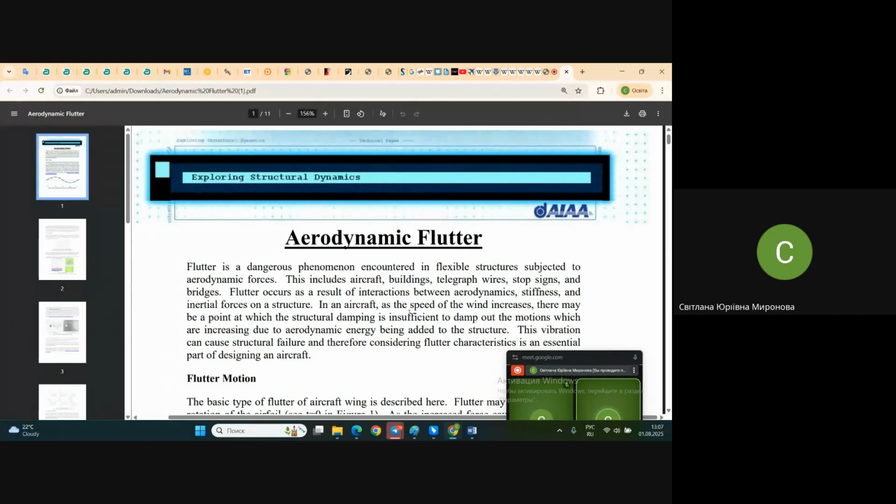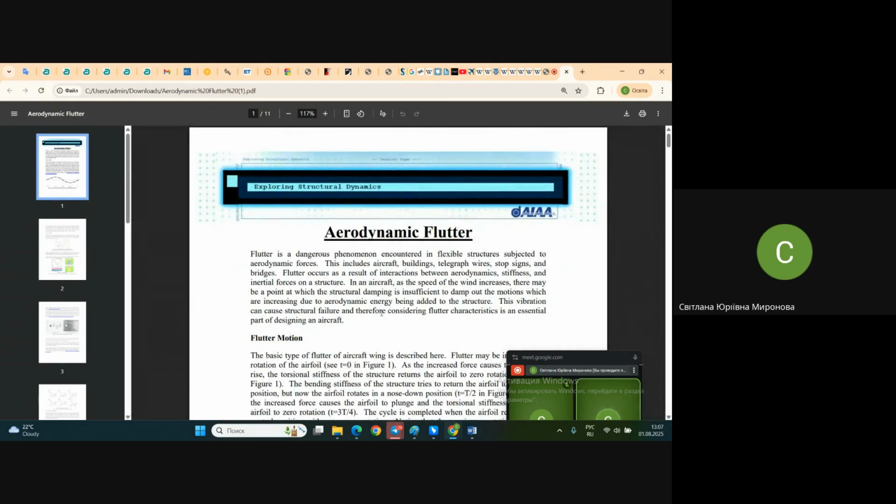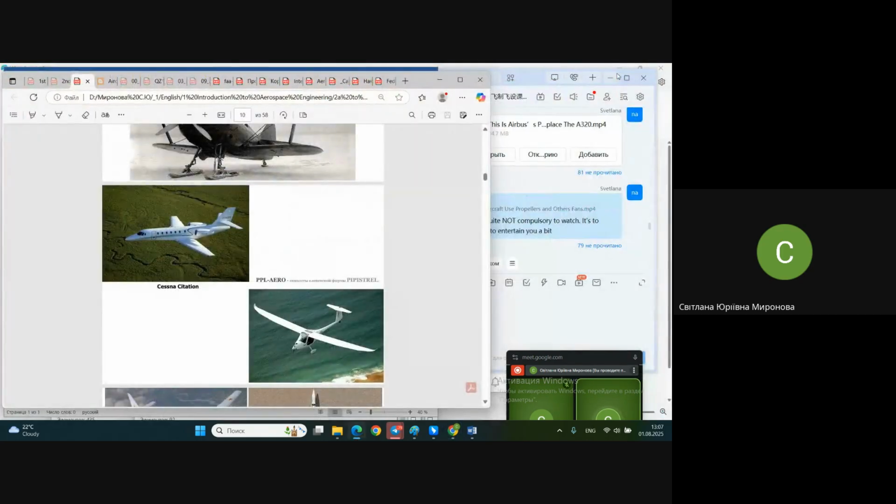Self-oscillation appeared due to the wind, and this self-oscillation is continuous and increasing in amplitude just because it coincides with the inner frequency of oscillations of the structure, like such an unlucky case. And how to work against the flutter, let's say, to increase stiffness. But as I already said, increasing the whole stiffness is not a good way to solve this problem.